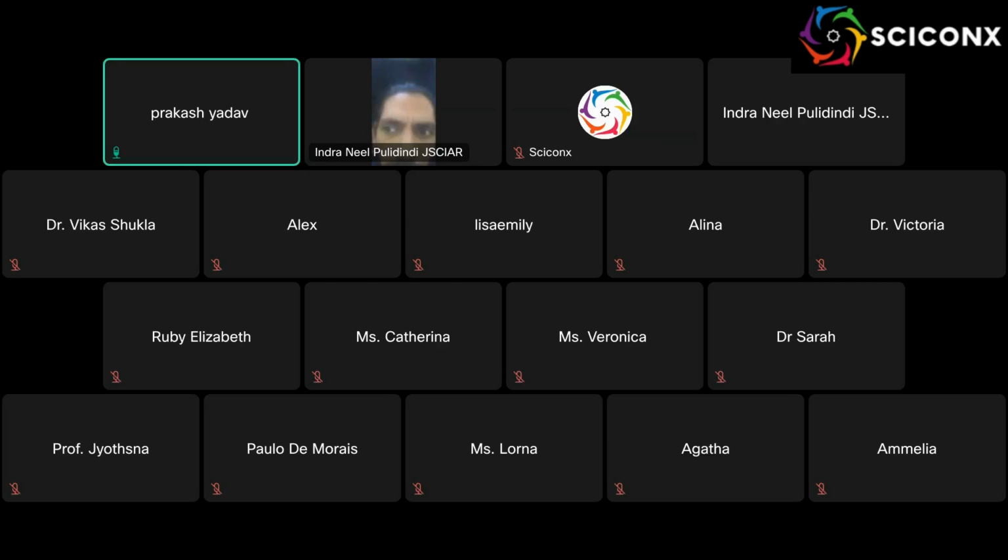So we only use it a single time. If your sensor is a chemisorption type, mostly biological types of sensors, it is only single use. But when we talk about physisorption sensors, we can use them multiple times.